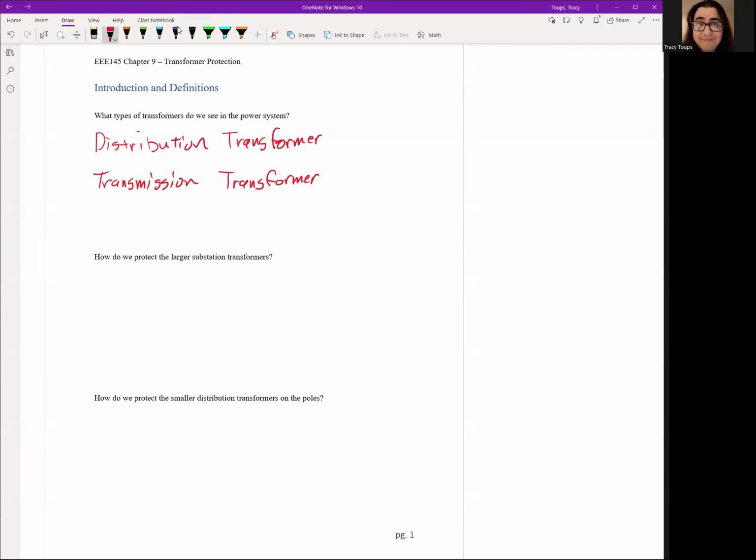They can convert the voltage from a higher voltage to a low voltage for distribution, or from a higher voltage to a medium voltage level on the distribution grid. For example, 230 kV to 115 kV or 115 kV to 69 kV. You still need a transformer between any two voltage levels.